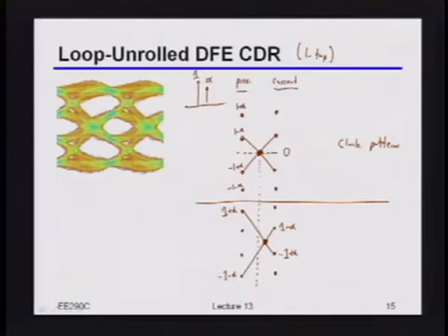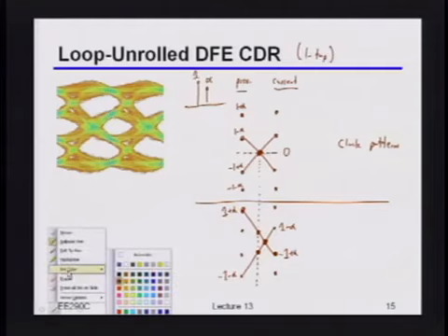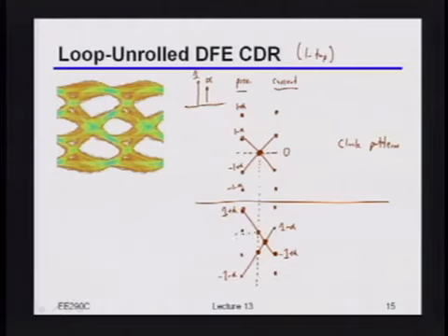Okay, so what that basically says is that now, if I want to make this thing work, what I should do is, on this arc, meaning on the arc that goes from 1 plus alpha to -1 plus alpha, instead of deciding whether it's early or late based on slicing at 0, I should slice at wherever that voltage is that crosses that dotted line. Okay, so I'm just going to draw a dotted red line there, and another dotted red line here. Turns out if you look at it or think about the math a little bit, that dotted red line crosses at plus alpha.